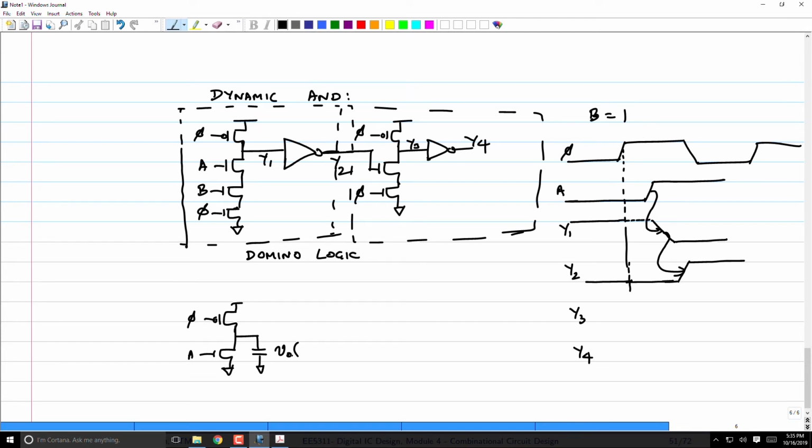VC of 0 minus. Now there is a pull-up path to VDD through leakage of the PMOS. Then there is a leakage through NMOS. These two are going to fight and the eventual value will actually not come down all the way to 0. It will come to some intermediate value between 0 and VDD depending on these two leakage currents fighting.